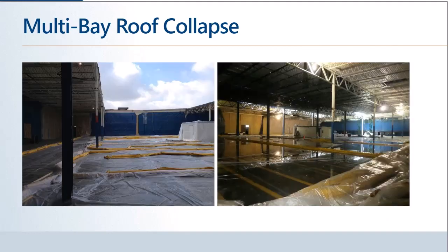So getting back to the repair, you can see once we kind of cleared away the debris field, it was just like we mentioned, just 2 open bays that needed to be put back, and the rest of the structure had fared quite well. That's on the left. On the right, we're installing that new steel and the new joists. Still haven't been painted, so they look a little bit darker than the underside of the rest of the building, but a pretty clean, easy application of IEBC.